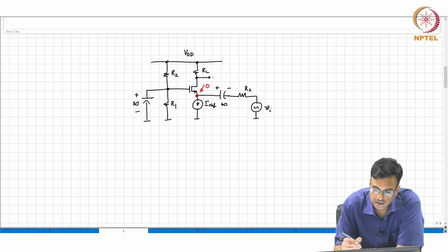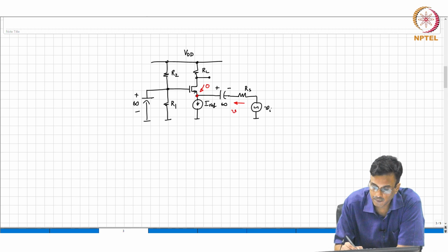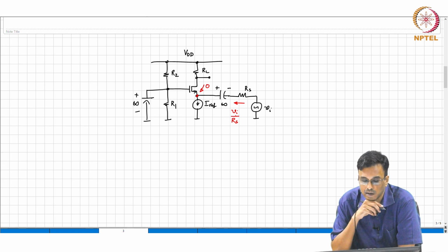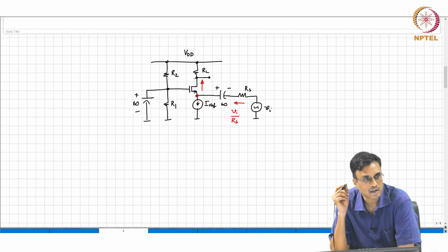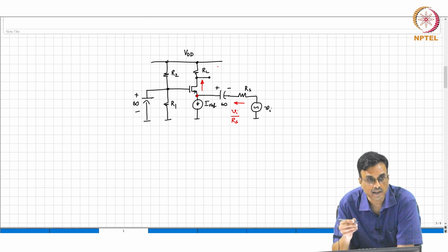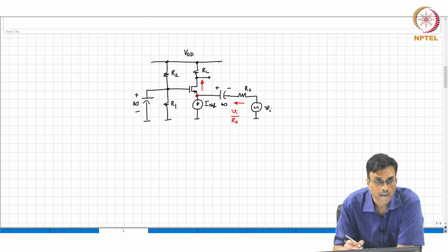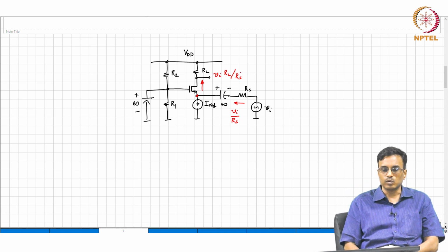0. All right. So, what is the incremental current flowing there? Vi by Rs. So, where does that current flow? IRF is anyway open circuit in the incremental network. So, that will flow through the RL. So, what comment can you make about the incremental voltage at the load? Pardon? Vi times RL over Rs. Again, you can just look at it and then tell the answer.